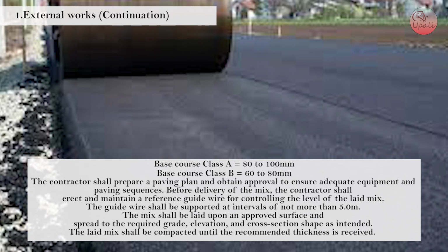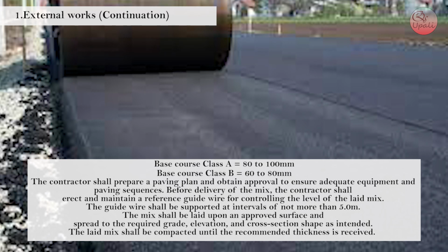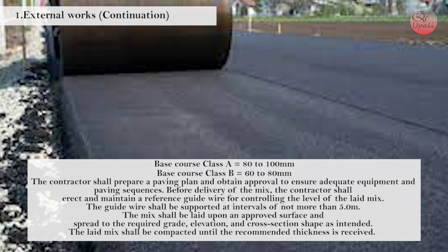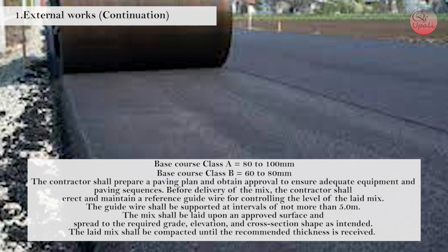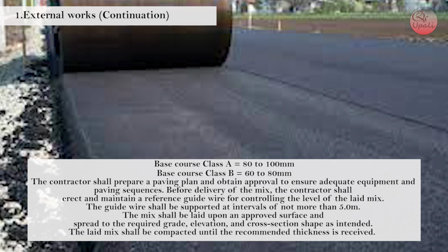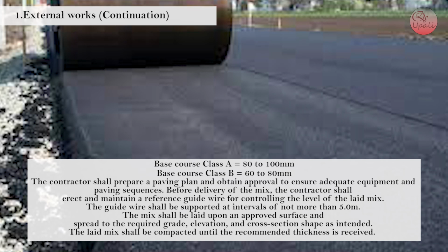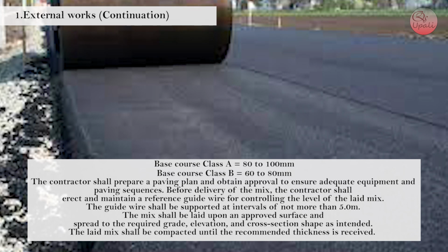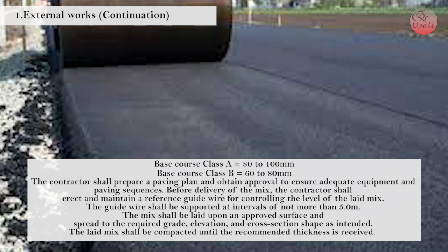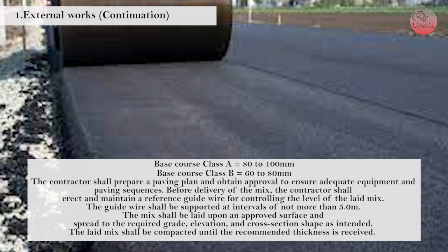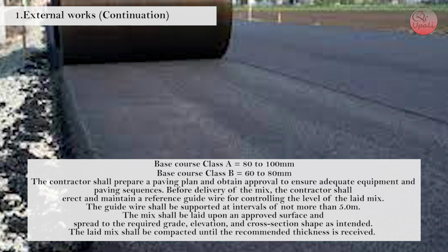Before delivery of the mix, the contractor shall erect and maintain a reference guide wire for controlling the level of the laid mix. The guide wire shall be supported at intervals of not more than 5 meters. The mix shall be laid upon an approved surface and spread to the required grade, elevation and cross-section shape as intended. The laid mix shall be compacted until the recommended thickness is received.